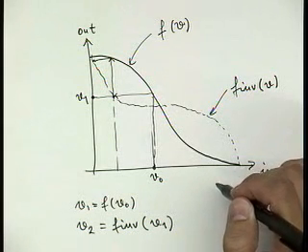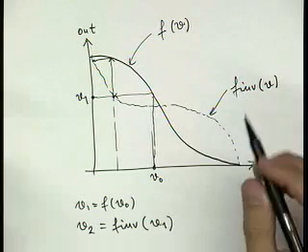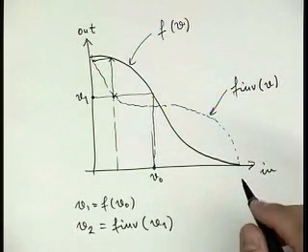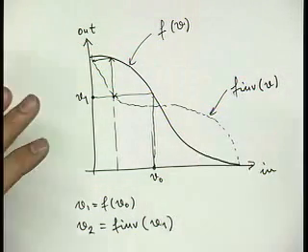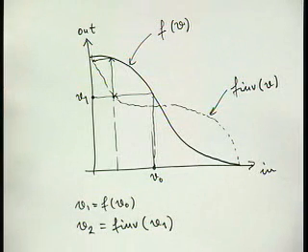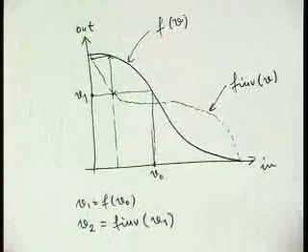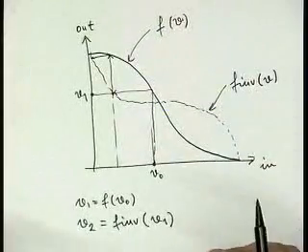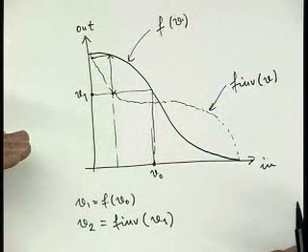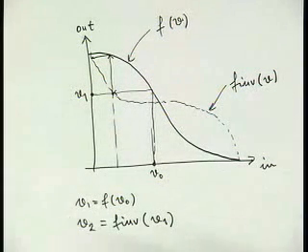If you have an even number of stages, then you will have a non-inverting function. If you have an odd number of stages, then you will have an inverting function. And for this gate that always ends up in one of the stable states, 0 or 1, we say that it has the regenerative property because it's able to recover from the noise disturbances and settle to a fixed value.